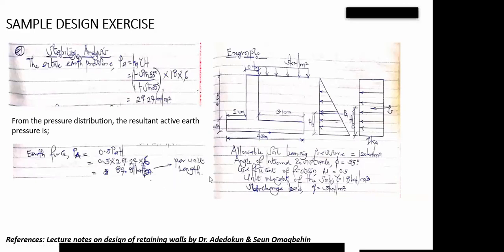And also, don't let the per unit length confuse you. You have to understand that whenever we are designing in civil engineering, all our design is always per unit, per meter length. What that simply signifies is that this is the amount of reinforcement that can cater for a meter length. And that is why you see that we always have per unit length. If you are curious enough, you may want to ask some. Obviously, a lot of people should know this though.